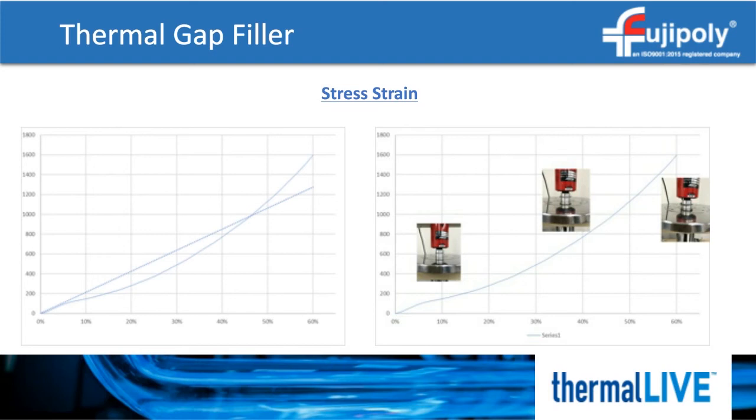Something else about the stress strain curve is the fact it's not linear. So using a single modulus value to describe the compression will often be inaccurate. You want to know where on the stress strain curve you will be working. Compressing beyond that point will cause the gap filler to densify and cease to flow. At this point, it's essentially a rigid material.